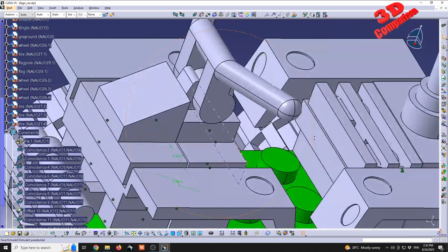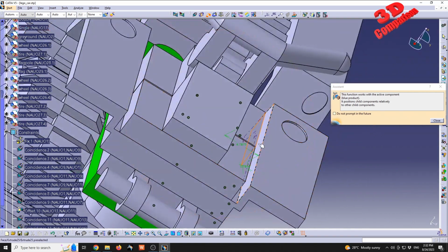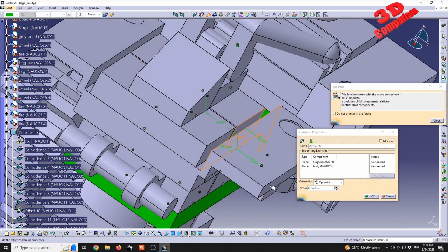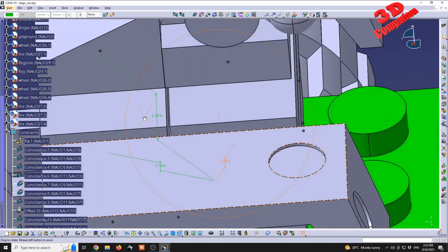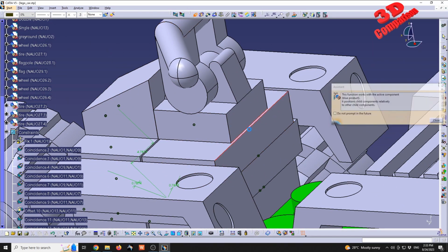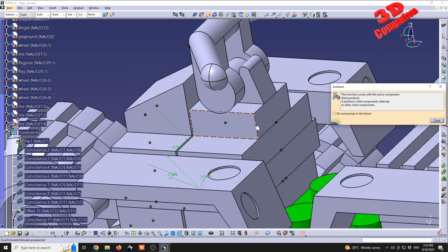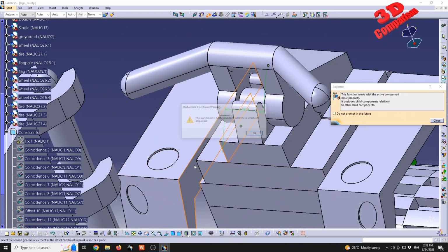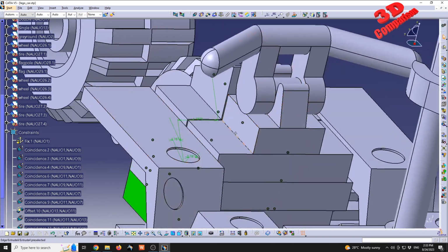And for this component as well, we're gonna maintain that offset, so between that face and that one. We're gonna see that it's the same offset value, so we can just use the value that we already measured, which is this one, and they should be at the same alignment. Afterwards, we know that we want this edge to be over here. And again, for this component, we are gonna maintain this offset. So we see that this is redundant since it's already added. So I'm just gonna cancel that.